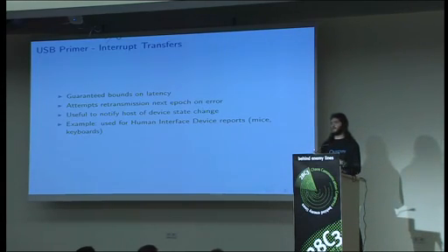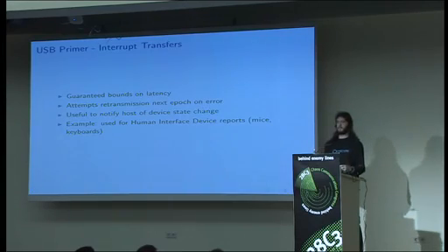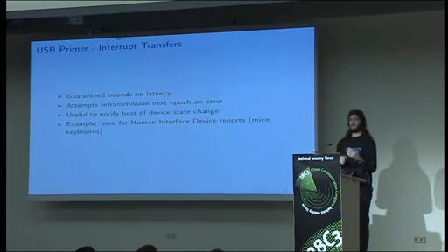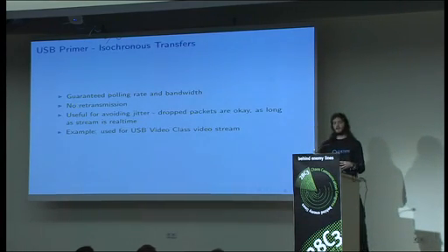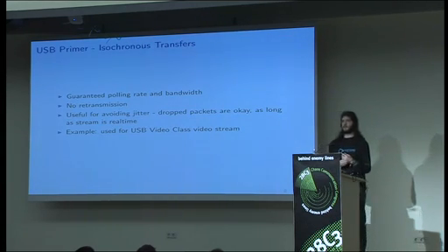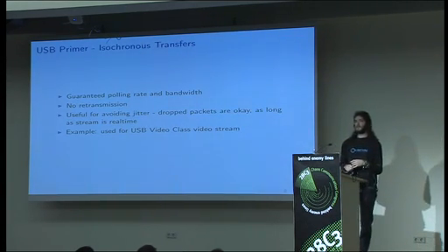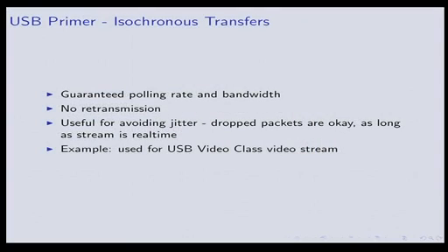If you have one of the car simulators, it can do force feedback, since you can also do host to device. So that's what these are usually used for. There's isochronous transfers, which are really useful for time-sensitive data. In particular, cases where you don't really care about getting every single packet, it's okay to drop a few as long as everything keeps in sync with real time. So there are video class and audio class specifications that build on top of these.